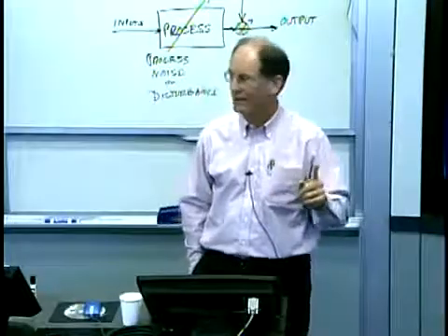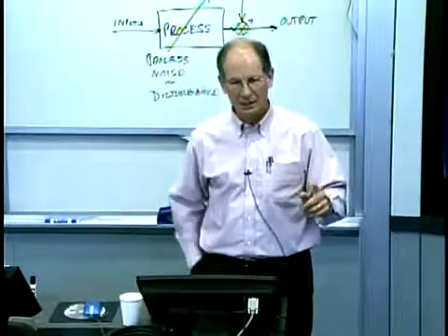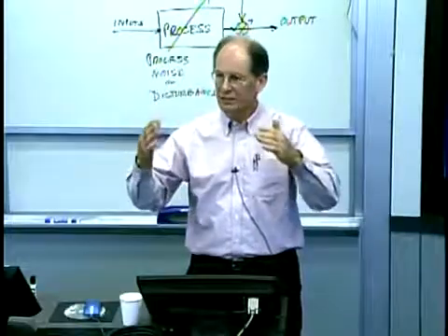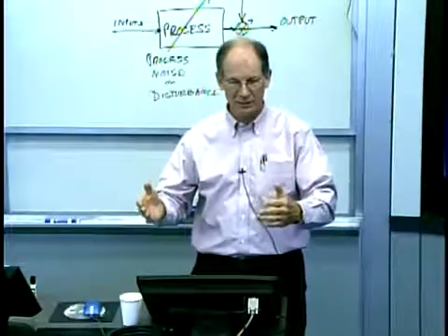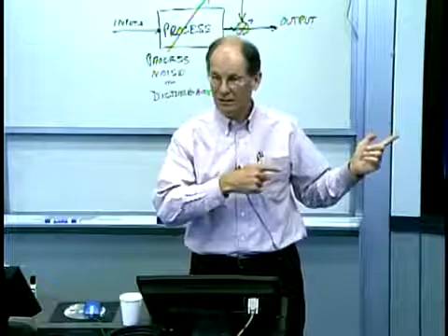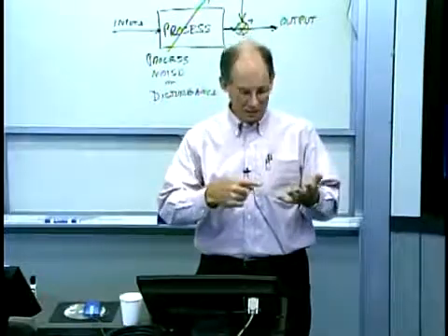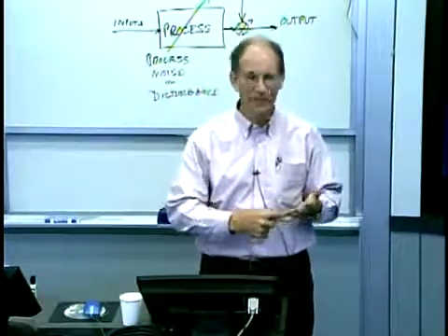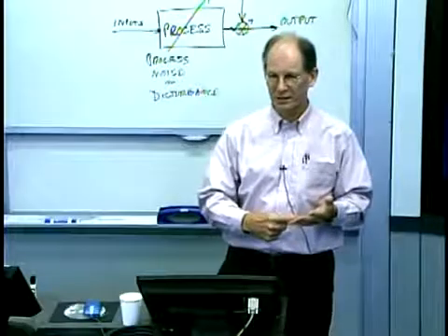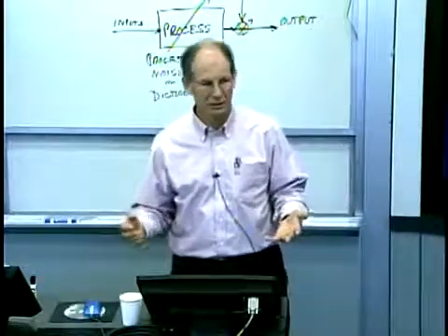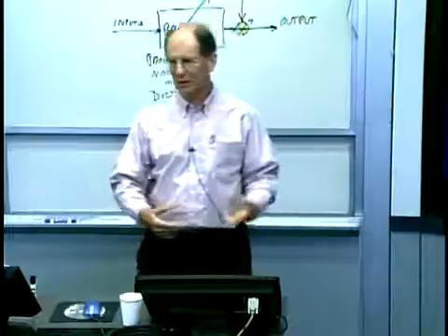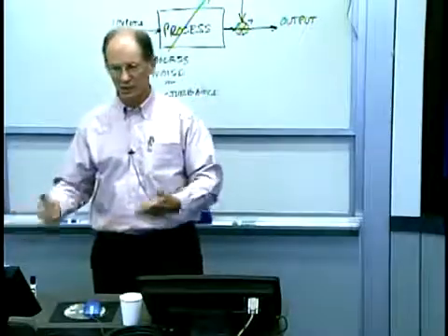The next thing after that is, okay, let's take that one level better, which is if something's going wrong with the process by the definition that's here, then that means that there's something out there causing the process to deviate that I could fix, and I could fix it pretty easily. Bad control over material variability, bad temperature control, poor maintenance of the machine, that sort of thing.